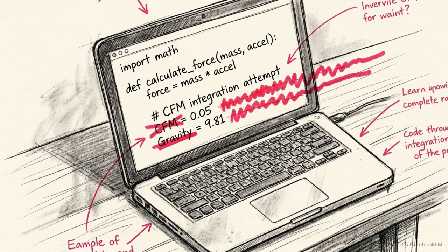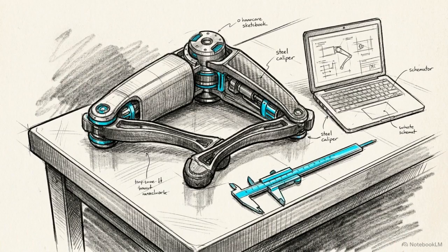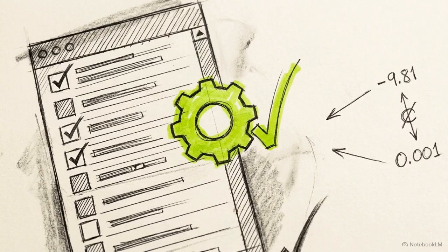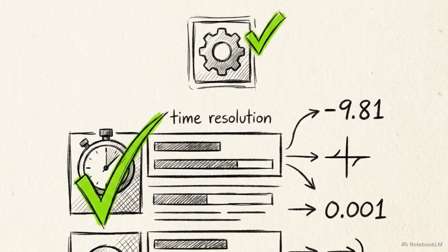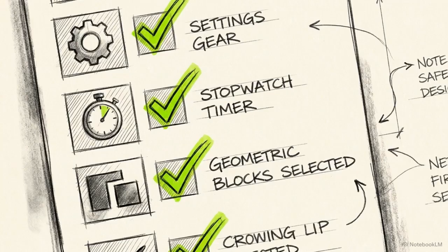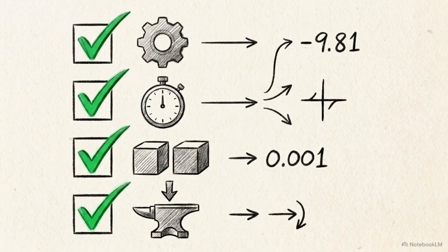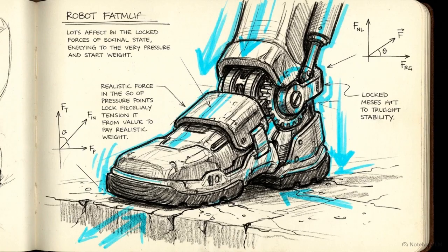To build a robust controller, you must strip away these forgiving parameters and force the simulation to mirror the physical lab. Use these Gazebo SDF settings. First, set your physics engine to Dart. Second, lock maximum step size to 0.001 seconds. Third, set soft CFM to 0.0, ensuring unyielding contacts. Finally, perfectly match virtual mass to hardware and set gravity to -9.81. This configuration stops the controller from finding shortcuts and forces it to learn real-world stability.